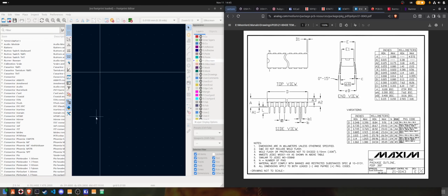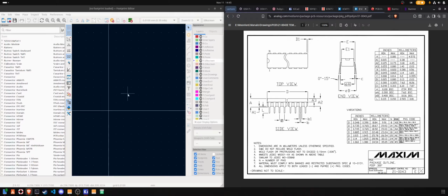You can make this part as easy or as hard as you want to. I like to assign my first pin to be 0, 0 on the coordinate system and then go out from there. It's worth sketching out your IC and then placing each via on this coordinate system and figuring out where you need to make it, so you can just go in here and make that adjustment.